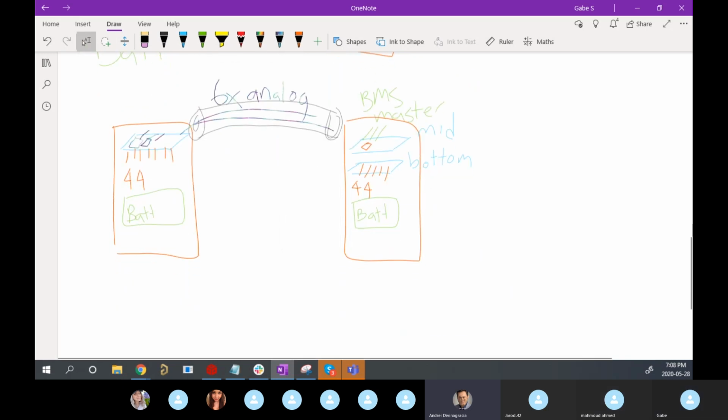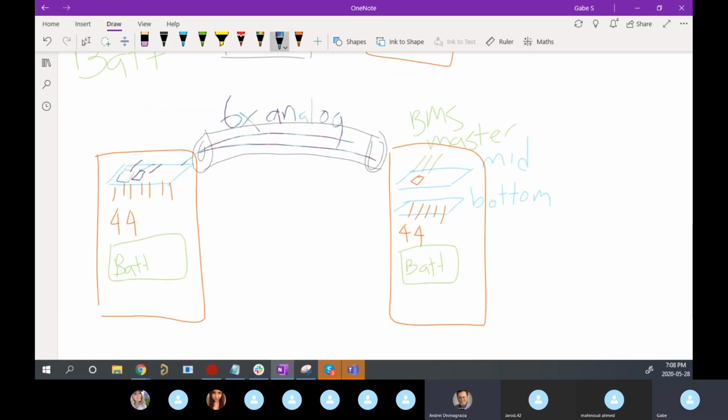Whatever the ADC outputs. Yeah, so that's definitely an option. You can just double, right? That's something we played around with. Is the middle board just an ADC, or is there something else there? It's basically the ADC and the voltage reference IC, and some filter. Oh, okay. You need 2 of those. Yeah, so you can put a second one, right? And then you send digital instead.